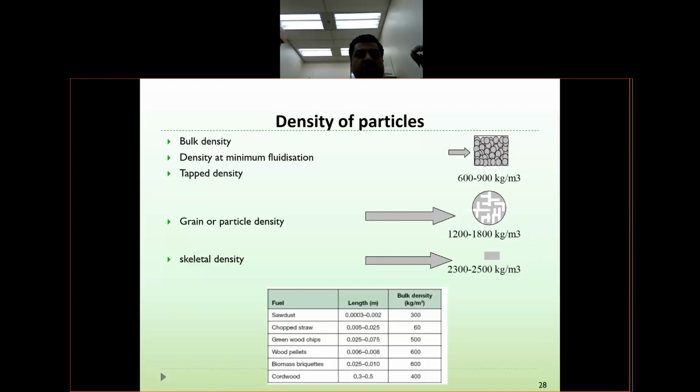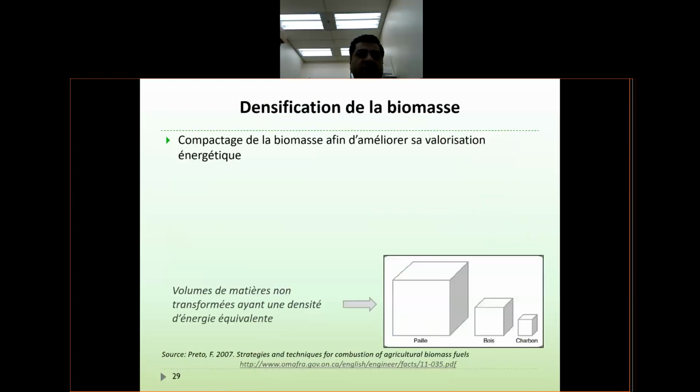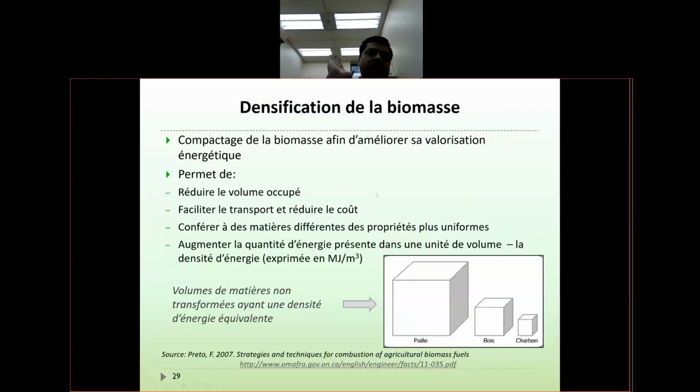The screen has some holes. Some of you already know what screens or sieves are. So biomass is fed from the top, and the hammers of this hammer grinder apply force to the biomass, so they become smaller particles, and then they get discharged from the holes of this screen, and then go to a cyclone in order to separate solids from gas.